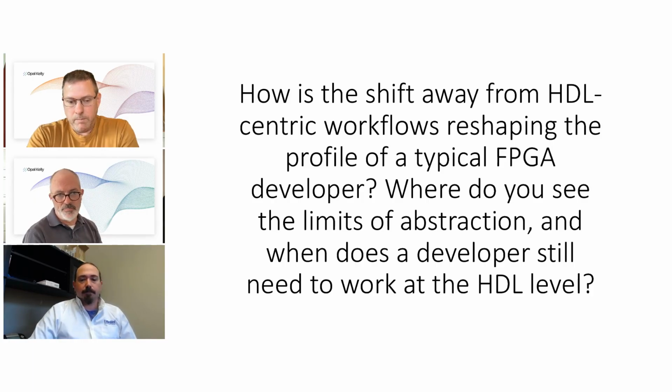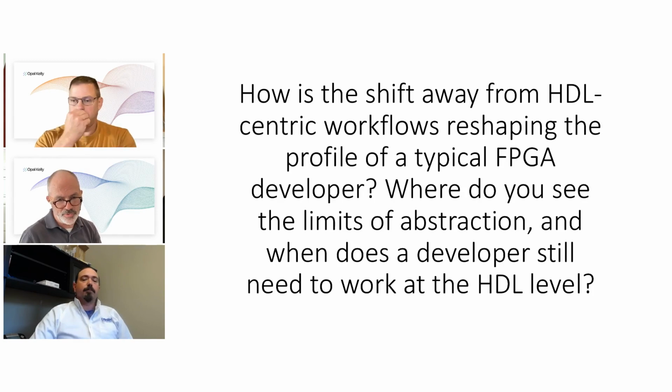We've seen others. MATLAB HDL Coder is an example of another way of essentially trying to loop in another set of developers, often scientists, mathematicians, other folks that are maybe looking to implement algorithms that they're developing in an entirely different environment, but to actually try and run them in real time with real data. And so these are different attempts at essentially trying to exploit the unique capabilities of FPGAs, and their inherent parallelism, which you don't get with a microprocessor-based system.